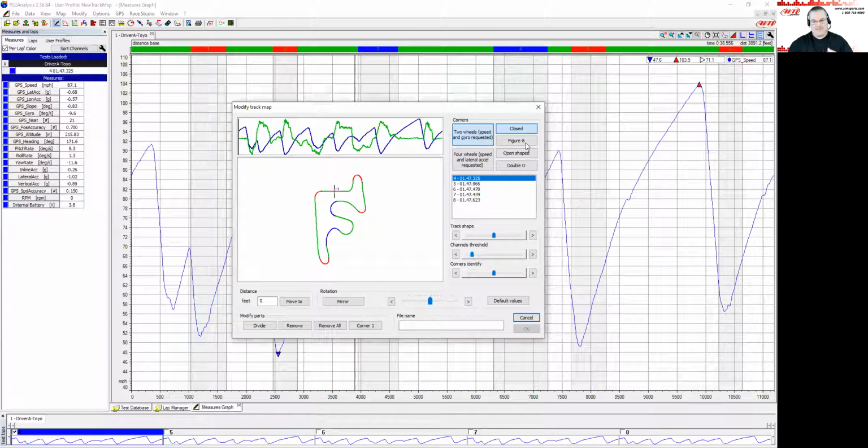With a GPS sensor, as you can see over here, we're creating a GPS gyro channel. That channel is there when you have a GPS sensor on board or built into your Solo or some of your other devices. If it's got a GPS sensor built into it or attached, this really is your best choice almost always. It's using the speed trace, mainly because it's a rollout distance, converting that into how far along the track you are.